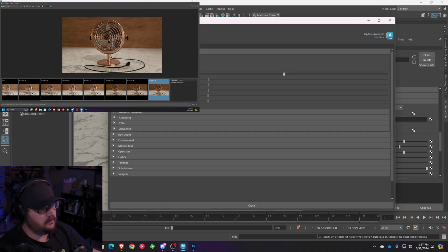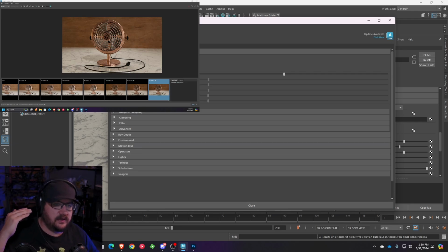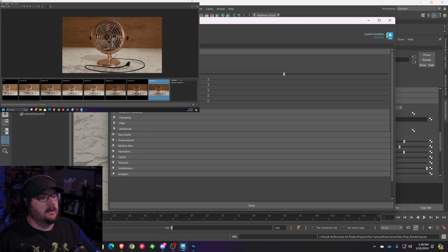If you're using CPU rendering, you're going to have to tweak a lot of these settings manually, depending on what you need. These are your samples. These are the samples that are being fired from the camera, bounced around the scene, and returned to the camera. With scenes like this, I will normally bump up to about 6 when I'm doing my final renders. That gives me 144 samples directly. I'm going to go ahead and turn off that preview mode right there.